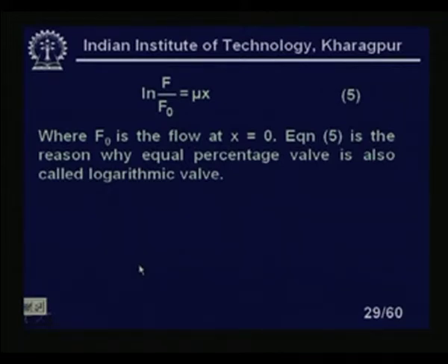This is very interesting. You see, the linear valve assumption we made initially is not exactly true. A control valve will never be used to totally shut off the liquid flow. There will always be some liquid flow through the control valve, especially in a double seated valve.